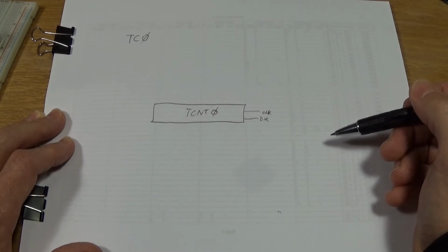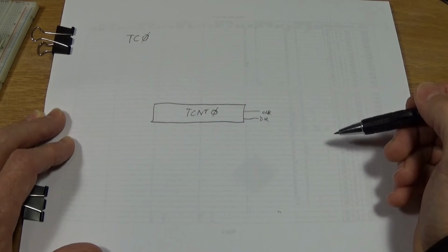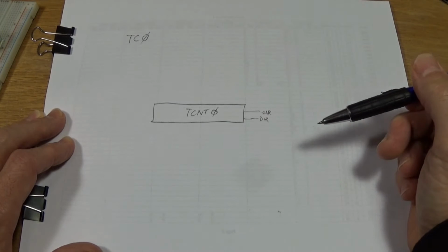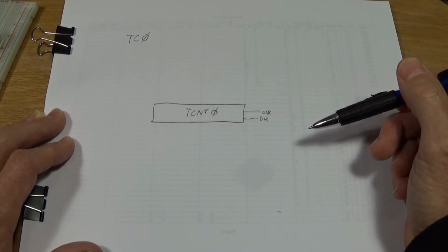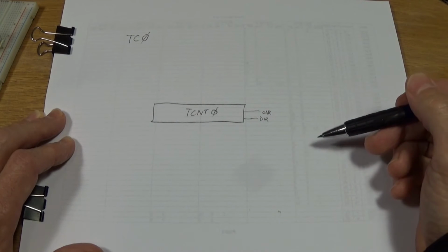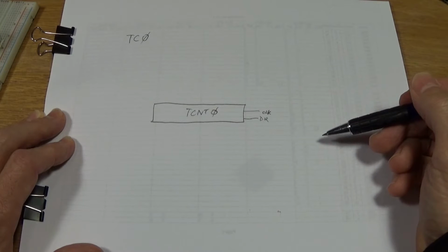That's a counter. A timer is something that runs at a regular frequency, and this is always incrementing at a constant frequency, and that gives you the timer function. And the signal for that comes from the main processor's main oscillator, FCPU, and in an Arduino that's 16 megahertz.